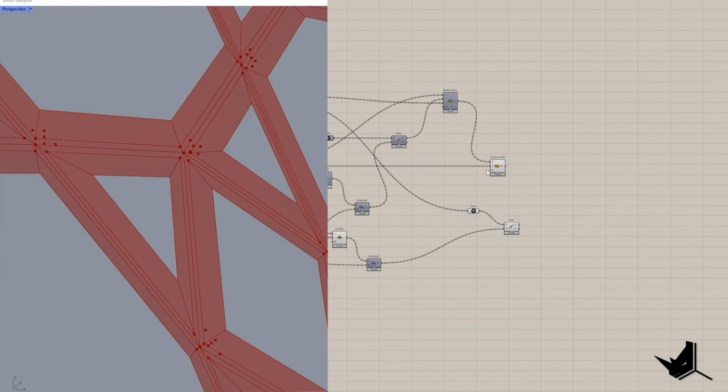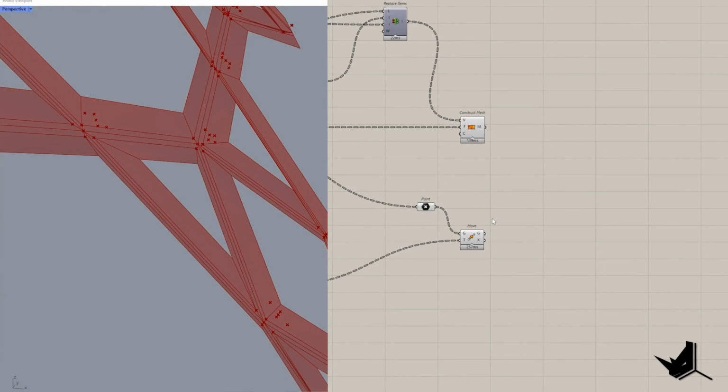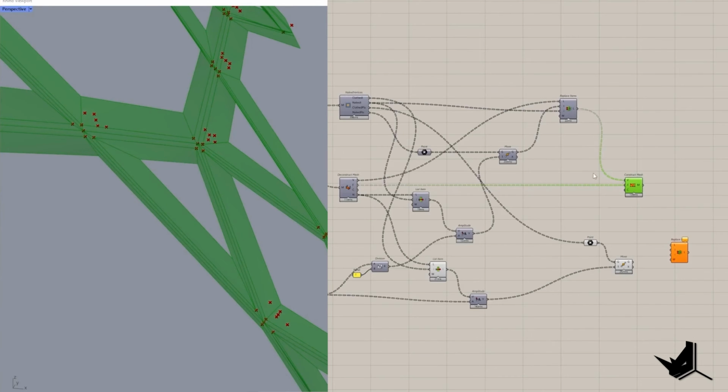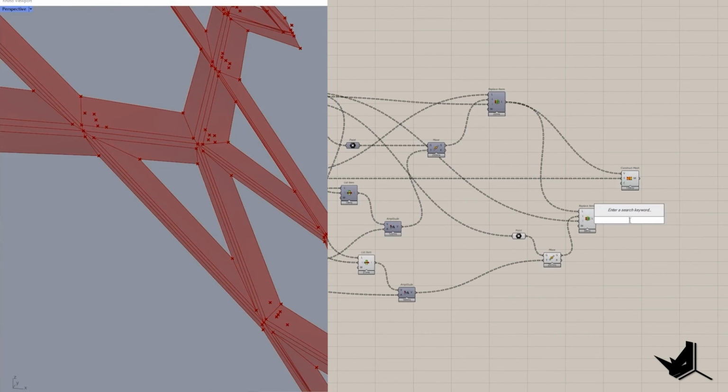the mesh. So to construct the mesh, we need to place these points at their exact position. So once again, I'm going to replace items, but now we're not going to replace the original mesh. I'm going to replace them with the indices from here, because I want to keep the new position of the naked points. These are the items that I want to replace with. And now we need to take their indices. Indices we can take from here. And now we can construct the mesh. So these are the vertices.